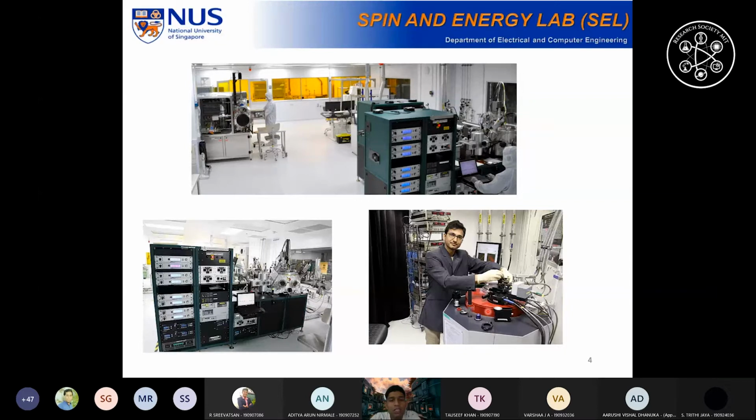Okay, so in this kind of chamber, we have a superconducting coil, which is kept below 10 Kelvin. The temperature of that superconductor is kept below 10 Kelvin using some combination of helium and so on. Okay, it's like a very cool refrigerator that you have at your home. Now, because the superconductor is below its critical point, that means what? It will have zero resistance. So you can pass very high current.